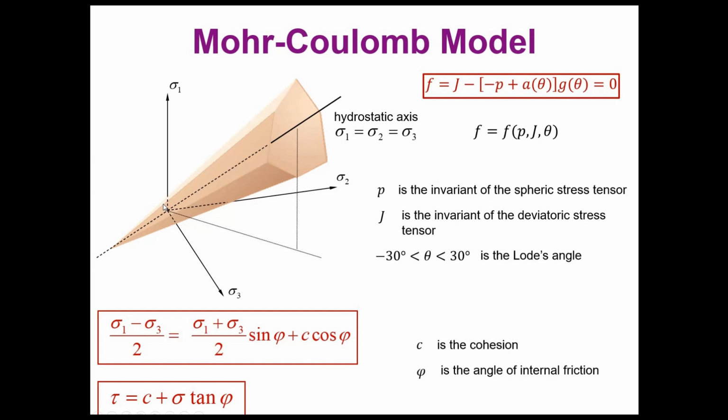When you start having tensile stresses in soils, it's very convenient to have this definition in here, because you will fail with very low loads that produce tensile stresses, because soils are unable to take any tensile stresses. This bigger area in here corresponds to the compression, so loads that produce compression.